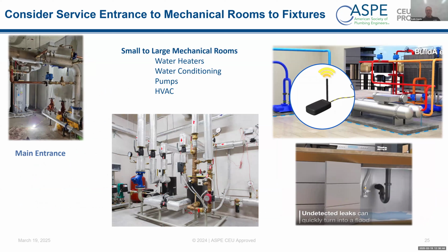On the top left there, it's a construction application. Of course, in construction, they've got whatever that is, a 10-inch line coming in, and they close those valves off at the top during construction and run a 2-inch line on the bypass that detects leaks through the construction process before they turn it over to the end user. With a 2-inch line, you can be more precise in your leak detection. The smaller the pipe, the better the leak protection, and the lower the flows that you can detect.